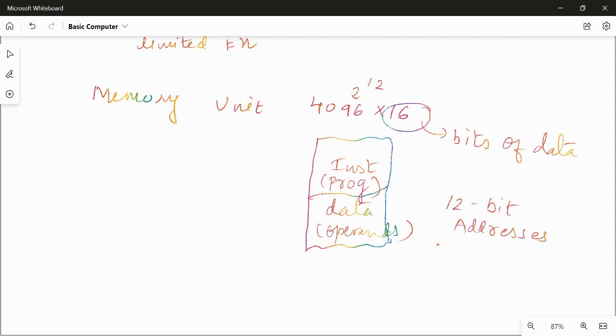Now, let us also understand what will be the format of instructions for this computer and exactly how many bits will be available to depict different parts of an instruction. So, if we talk about the instruction code for the basic computer, then we can assume that one memory word is sufficient to store one computer instruction. That means the size of one instruction would be 16 bits. So the actual bits would be 0 to 15. Now this instruction code will be divided into different parts.